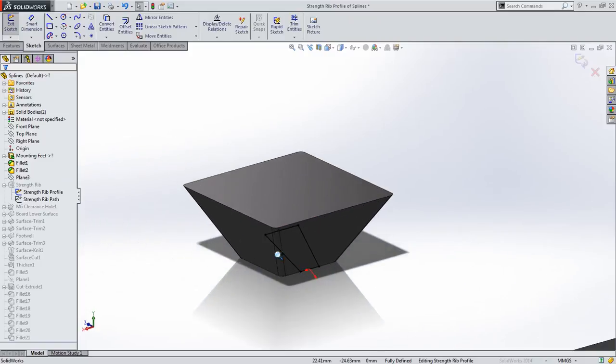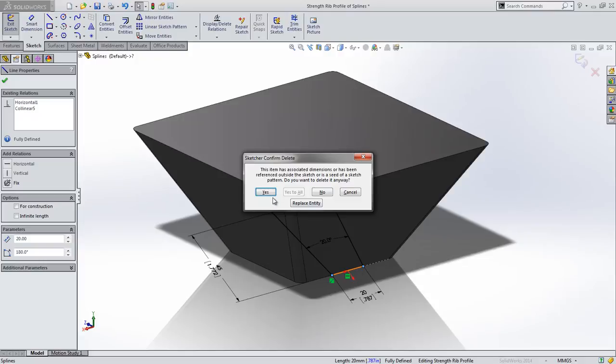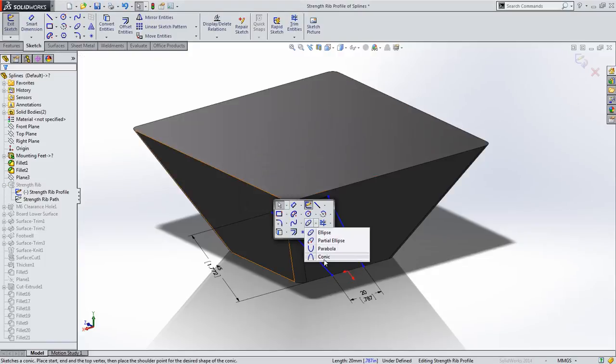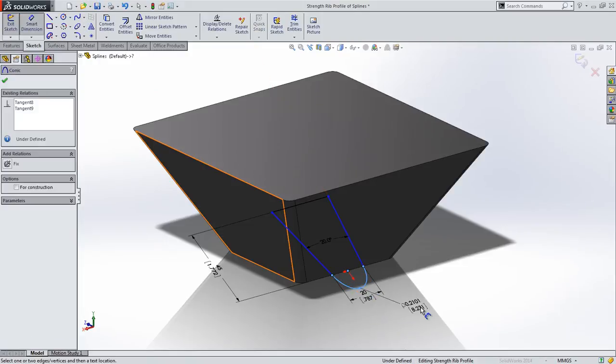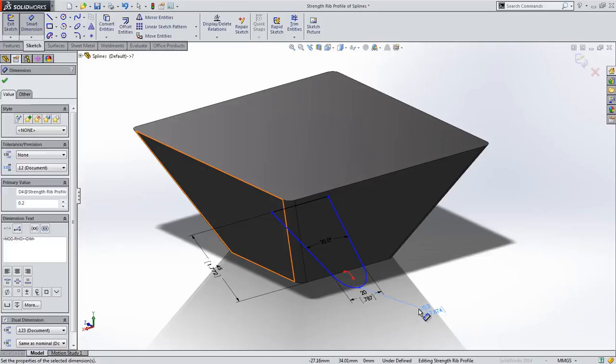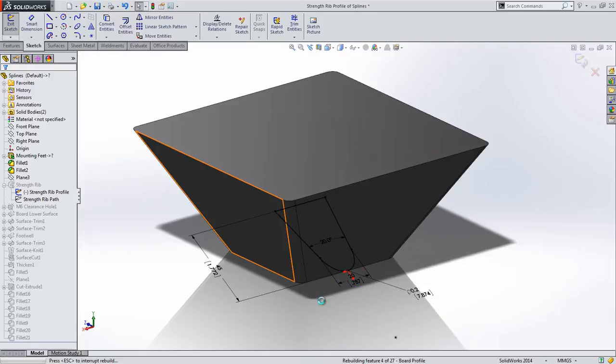We'll do that to the sketch profile used in the same feature. Like before, we'll remove the existing entity, and again, adding the conic is easy, as the sketch relationships are added automatically. And again, all that's needed is to add the Rho value, and in this case, we'll move the sketch geometry by simply snapping it into place.